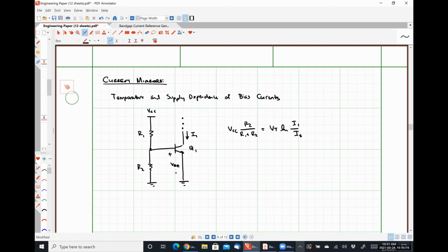So if your cell phone relied on this type of biasing, where the amount of current being supplied to your different chips and all that kind of stuff varied with the supply voltage, you could never use your cell phone once it got below a certain state of charge. It would be a very terrible design. So biasing in this way is actually really bad for high performance microelectronics because the supply voltage can vary appreciably, especially for portable products and stuff like that.